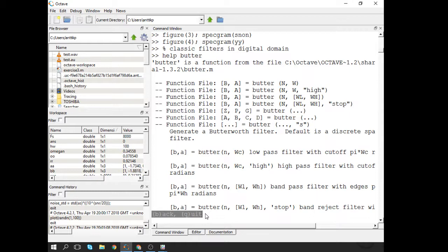So Butterworth filter, what was special about it? Hi-fi audio. It has flat, optimally flat bandpass response. Chebyshev, what was special about that? It's sharper. Bessel, never use it here. Bessel filter is in analog domain. It gives almost linear phase shift.